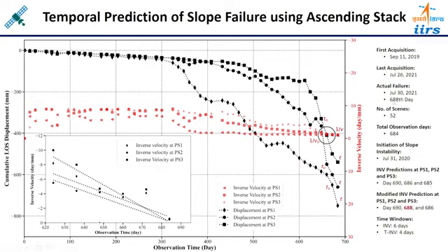So you see the actual event happened on 688th day, but according to the prediction it is the 690, 686 and 685. So you can say 2 days are coming before the actual event and 690 is coming after the actual event. So we are getting a mixed kind of prediction. This method is telling from 685th to 690th day, any day the event can happen. So it is basically giving an indirect hint to us that the landslide can happen from 685 to 690th day, any day. This is basically called the prediction window, and the actual event happened on 688th day.